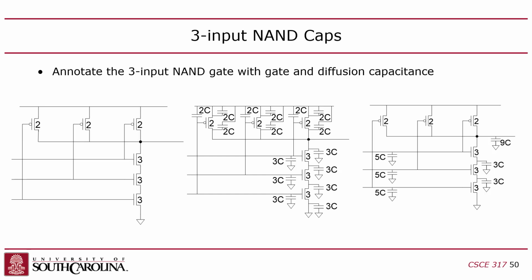So this is a source capacitor here. We've got to get that source capacitor, and that source capacitor, and that source capacitor, right? So that's our output. For this output, we have to consider those three source capacitors because they're all connected in parallel to the output wire, right? You guys with me? So that's 6C.